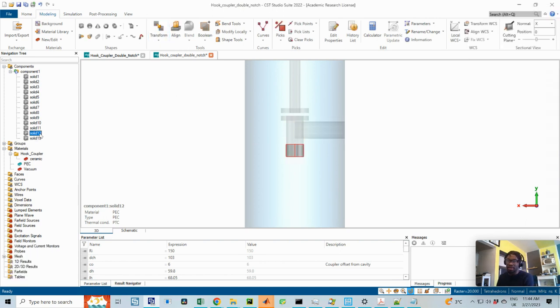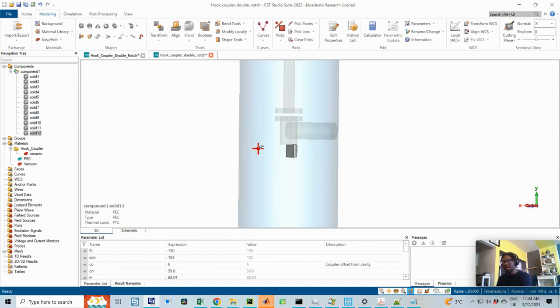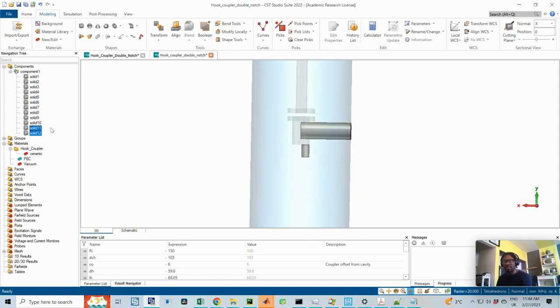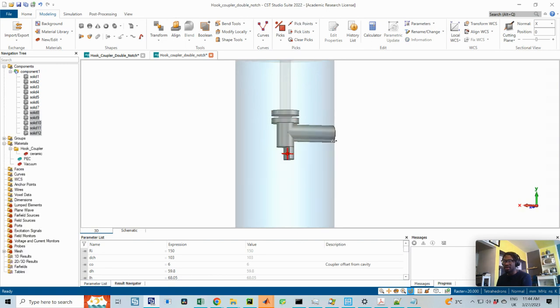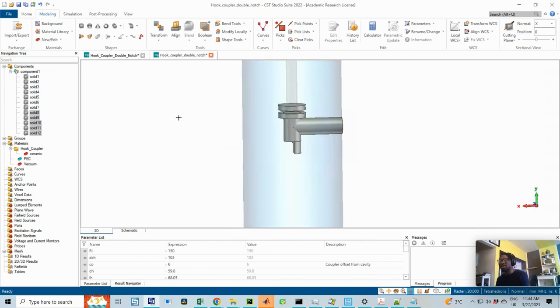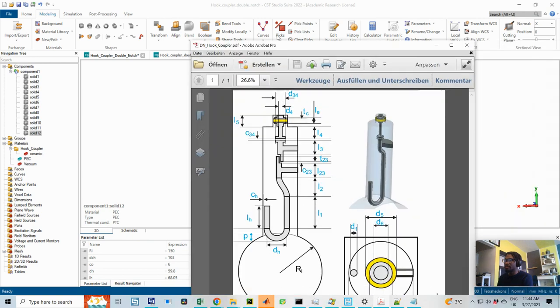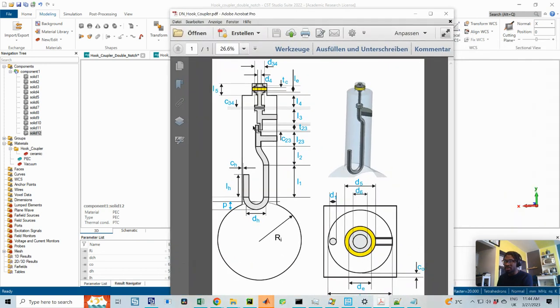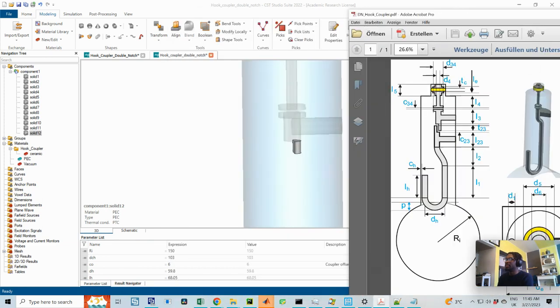So I click on solid 12, and I go to Boolean subtract, and I click on solid 13, and voila, this is what I have. If I'm viewing everything together, holding control and viewing everything, this is what I wanted. I'll do exactly the same thing for this bottom part of it. I'm going to model the cylinder first and then subtract the brick from it.